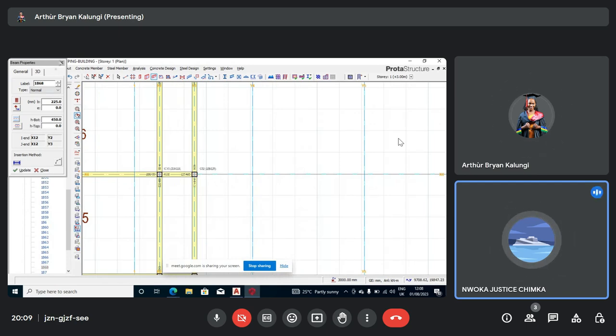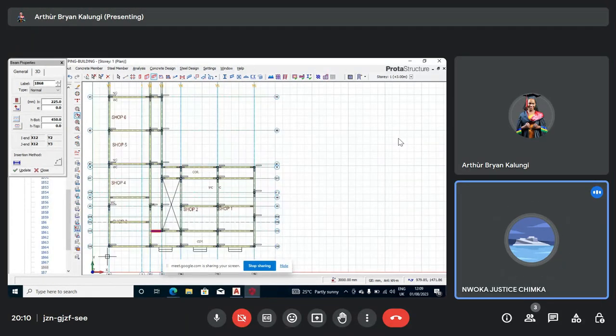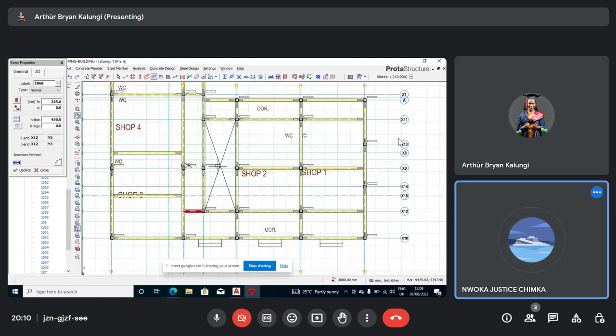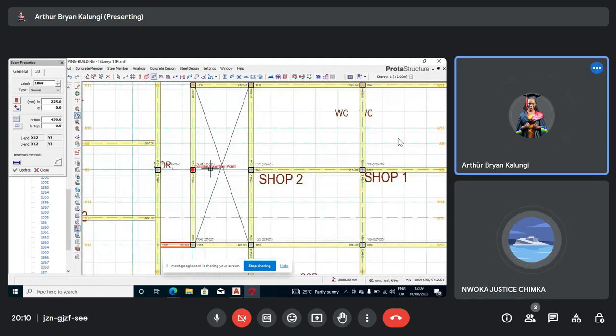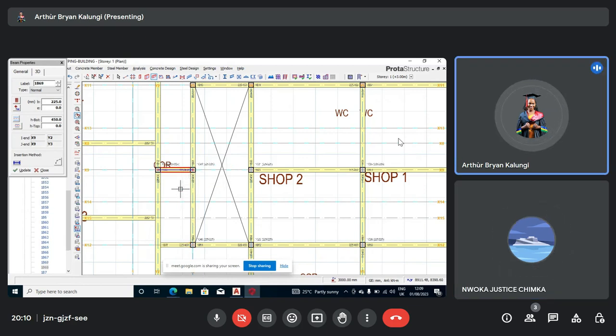But first of all, I think there is a place where we have not put a beam yet. Calm down. Near the staircase here, you should have a beam in between this long panel. You can see that it is long. From the column, go across there. Yes, because this panel is too big for a slab. So divide it into two. Yes, that's fine.